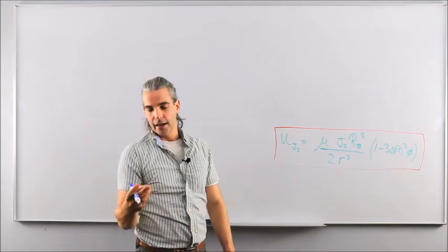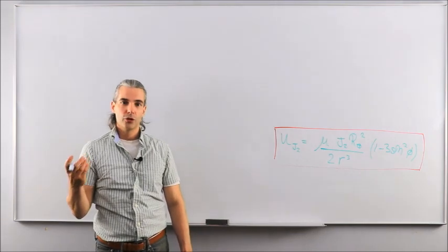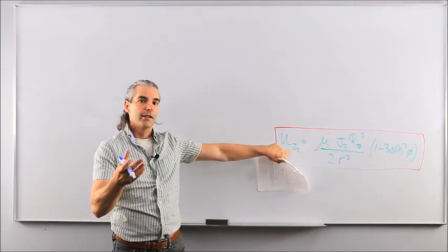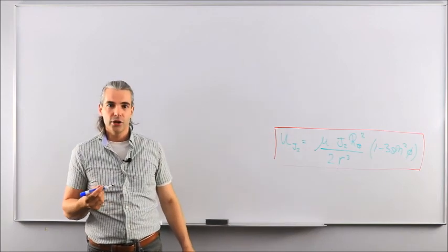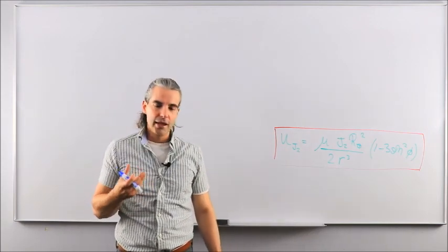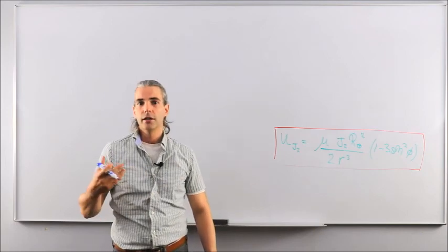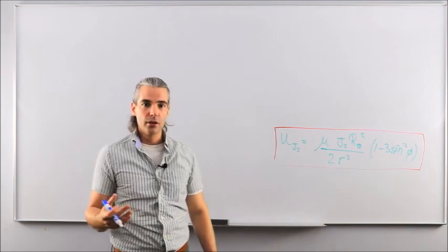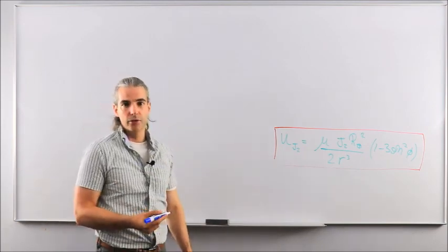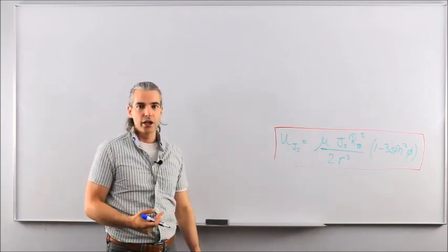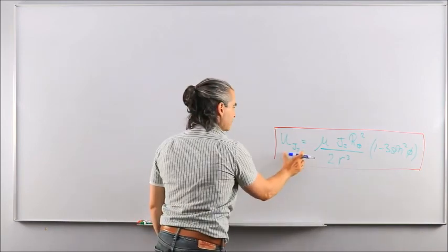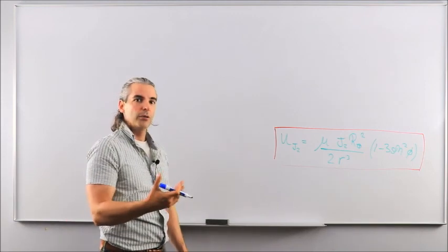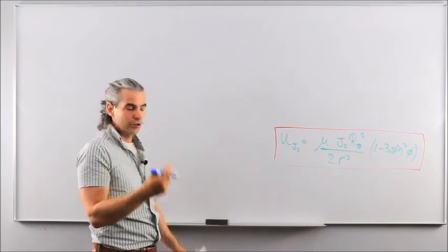Then look at the x, y, z components of this perturbing acceleration vector related to J2 and plug those into our Gauss variational equations to better understand the effects of J2 on each of the orbital elements of the spacecraft, which will be time varying, as you know. And then we'll also calculate the secular variation and the average rate of change due to J2 specifically on our orbital elements. All of this will be done through the tool we developed last time, the Gauss variational equations.